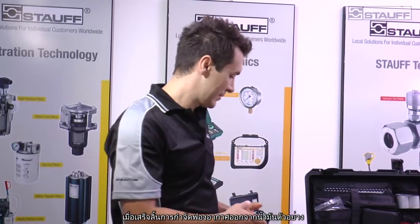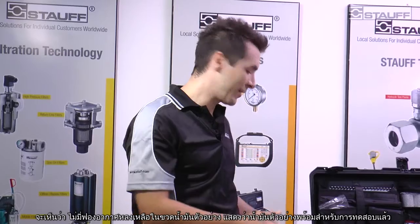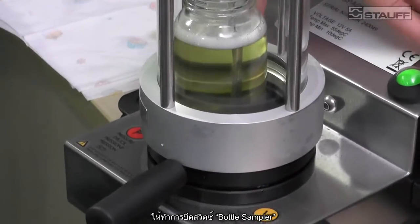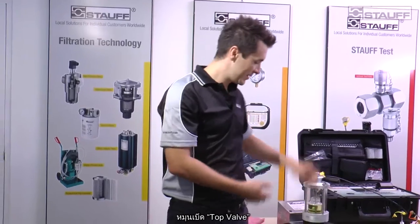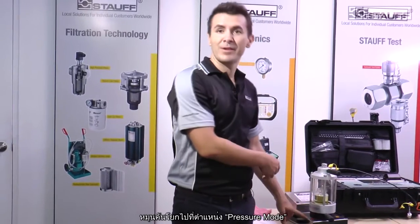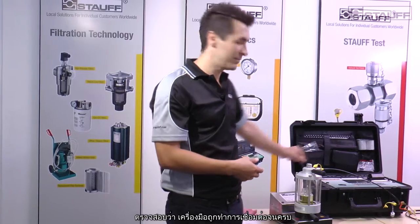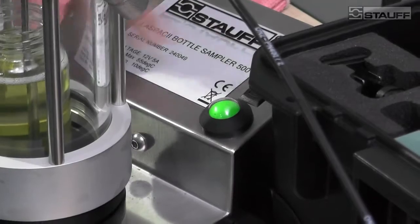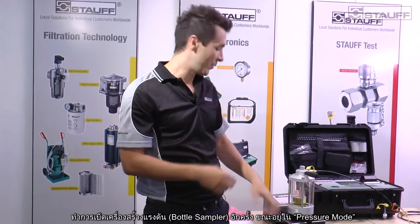Once we finish removing all the air bubbles, so there's no more bubbles down the bottom, so now we are ready to turn it off and then commence the test. So we turn the bottle sampler off, open up the top valve, change the handle to pressure mode. When the machine's already set, make sure the machine's turned on, and then start the bottle sampler in the pressure mode.